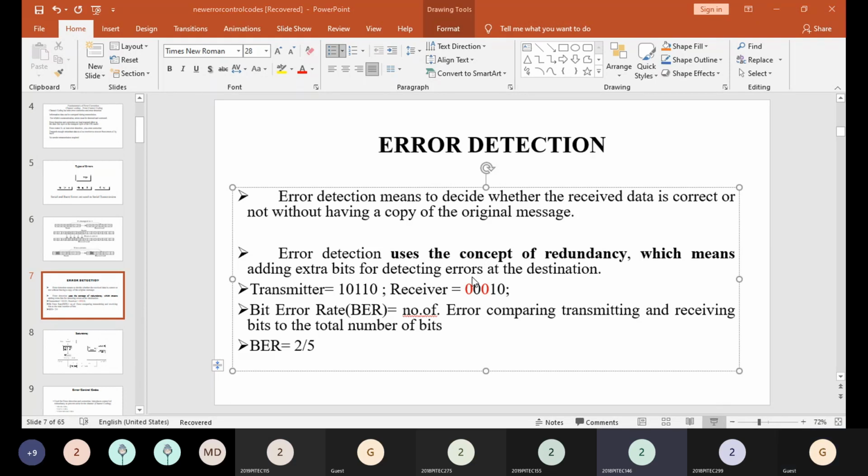Now, the important thing in error control coding is that you will be having redundancy. You have these sets of bits. These bits can be transmitted either by using linear block codes, or you can transmit them by using convolutional codes, by using generator functions. Generator functions are polynomials, either in the transform domain approach or in the time domain approach, whichever you are aware of. Then you need to have the redundant bits, so you need to check with redundancy.